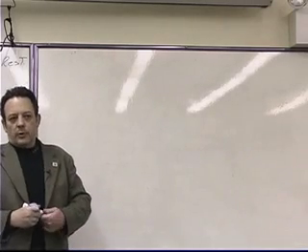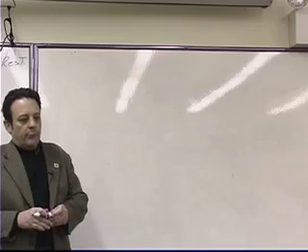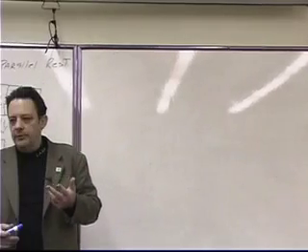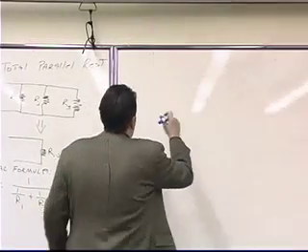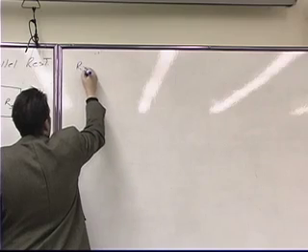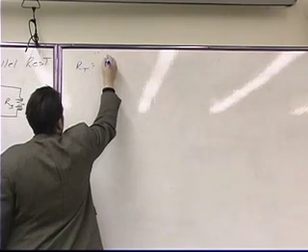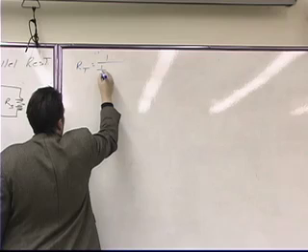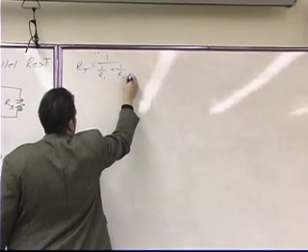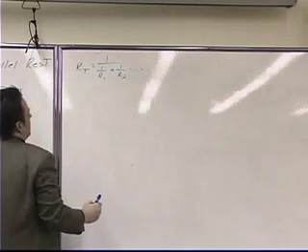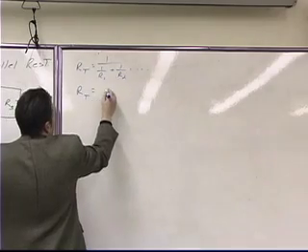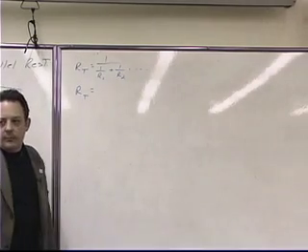Let's practice for a moment with the 3 different forms of the formula for finding equivalent parallel resistance. The first one I wrote down when we began: R total is equal to the inverse of 1 over R sub 1 plus 1 over R sub 2, and so on. The second one is what we call the product over the sum.